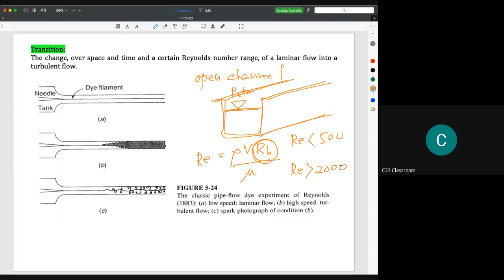Okay, and then we are focusing on the boundary layer. So let's say we have a boundary layer here. We have the laminar, then we have a transition, and then we have a turbulent. The transition here means when the laminar boundary layer changes to turbulent boundary layers. But in a real application, normally people will assume that the transition region for the boundary layer is quite short, so sometimes we neglect it.